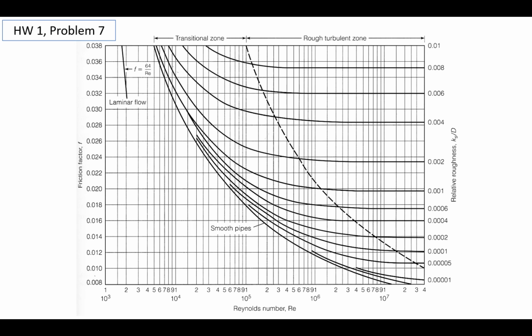Obviously there's a little bit of flexibility built in anytime you're using a graphical figure where you're running your finger over the page. I obviously have a little bit of tolerance for variation, but I wanted to illustrate that you can't be too sloppy, especially because if you have a Darcy-Weisbach problem on the FE exam, you're not going to be solving the Colebrook equation on the FE exam. You probably won't even be using the Jain equation on the FE exam. If you have any problem using Darcy-Weisbach, they're going to have you refer to the Moody diagram to look up F. And so you'd need to be precise in using the Moody diagram, otherwise you get that question wrong.